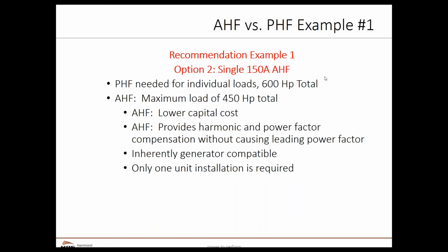The AHF should have a lower capital cost and installation cost because you have 1 active harmonic filter and 1 installation, whereas with the passive harmonic filters, you have the cost of 12 individual passive filters as well as the installation cost for those filters. And in both cases, they're going to meet IEEE 519 and address any power factor concerns.